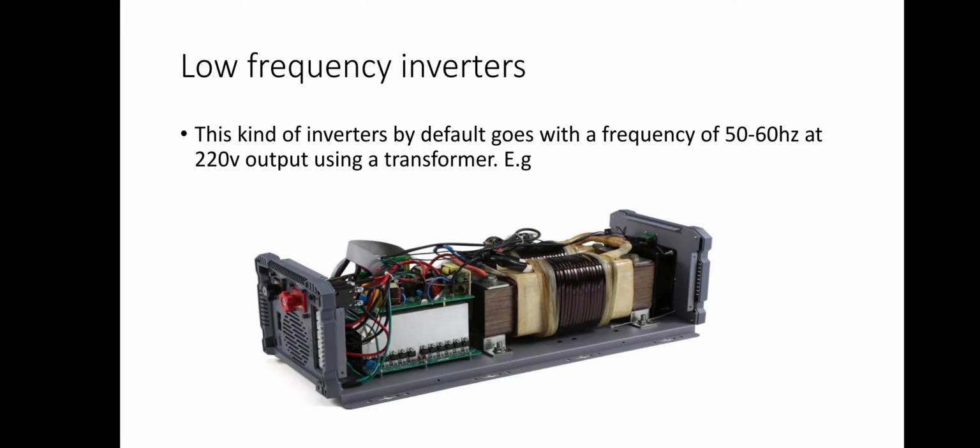Now the transformer you're seeing here, most of these ones are called UI transformers. So if you check carefully, there is the MOSFET board beneath and the driver board on top. Now once this inverter is connected to a battery, it does not go through any other conversion. It goes directly to the driver board. The driver drives the MOSFET, and the inverter gives out output.